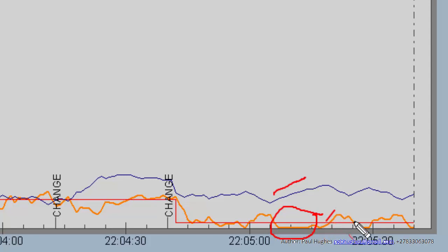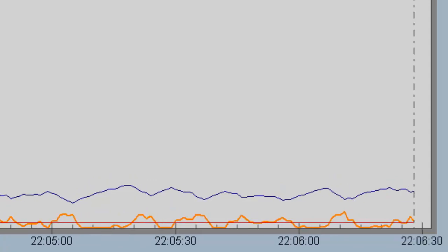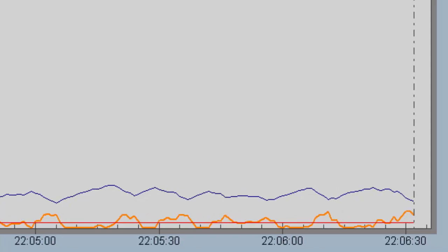The flow reading recovers, and because it suddenly recovers, it overshoots. The output goes down again, and once again it goes to 0. Then it goes up, and you start getting the seesaw effect, which is quite common in a turn down case. And that's how it looks as it continues. So this is actually fairly well behaved. It's normally a lot worse than this.